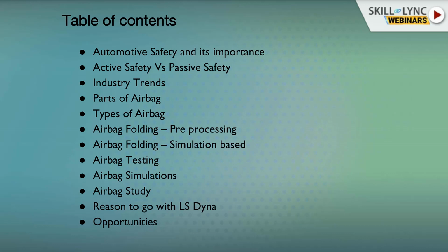In airbag folding we will discuss two types specifically: a normal folding done before an FEA simulation is conducted, and then a folding which is based on simulation. This folding type is similar to real-time folding, where we have tools and a setup for the folding process before the actual deployment behavior test.